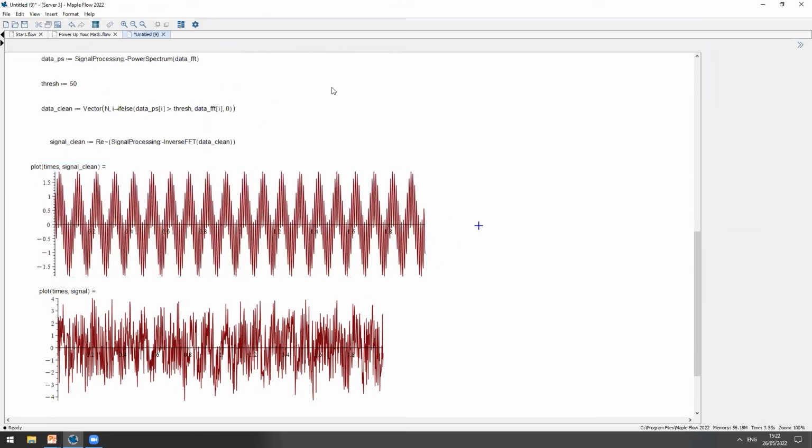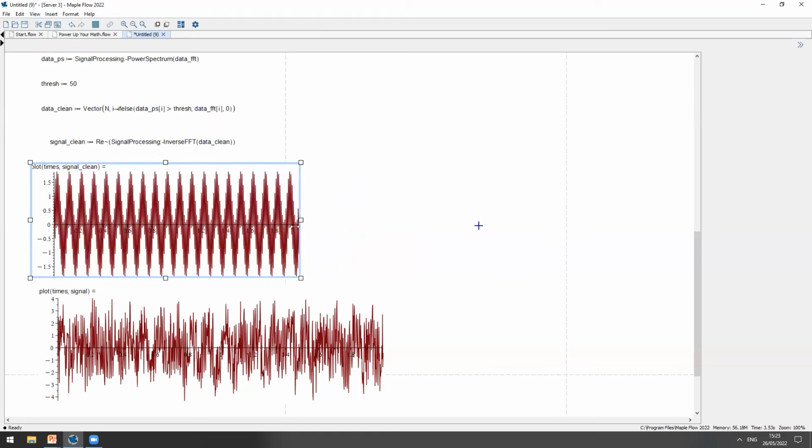Of course, once I've created an application like this, I might want to present it nicely, convert it to a PDF. So what I can do is go to the View menu, select Print Extents. I see vertical and horizontal dashed lines. These delineate the boundaries of my chosen page size.